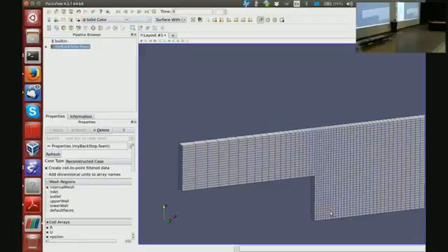Okay, but if you make it really, really thin, it is silly to look at on the screen. And the second thing is, I have to calculate the volume of these cells, so I want them to look reasonable. So the cell aspect ratio of that cell is within, I don't know, 20 to 1, right? If I make my geometry this wide, it would be 1,000,000 to 1, and I'm going to have a round-off error in the calculation of the volume. So there is no guidance really of how thick it needs to be. Just make it look pretty.